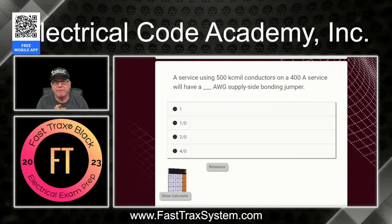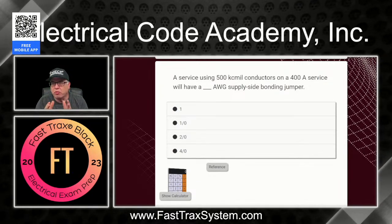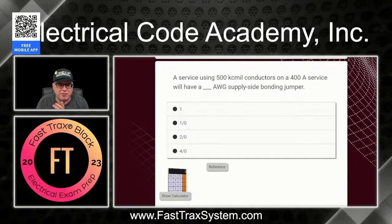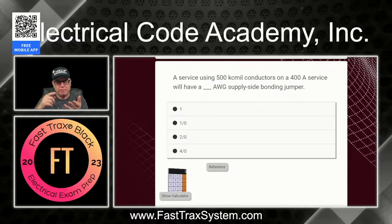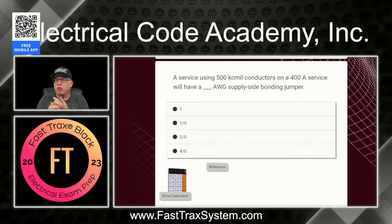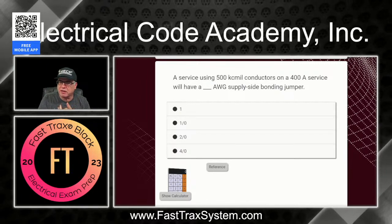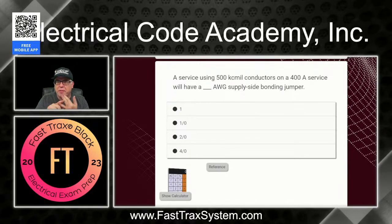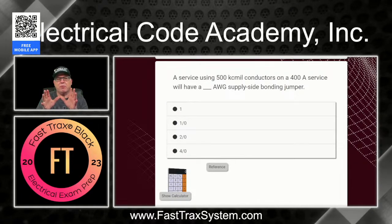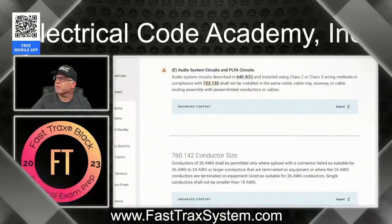This is why I tell you folks, it's so important to learn tables and certain things in the code and do your best to commit them to memory. Remember, 250.66, grounding electrode conductor sizing, okay? 250.122, equipment grounding conductor sizing. 250.102(C), minimum size for the grounded conductor, supply side bonding jumpers, main bonding jumpers, system bonding jumpers, all covered by that table. That's where we're going to go. So let's go to the code. And it's a 500 that's being used, okay?